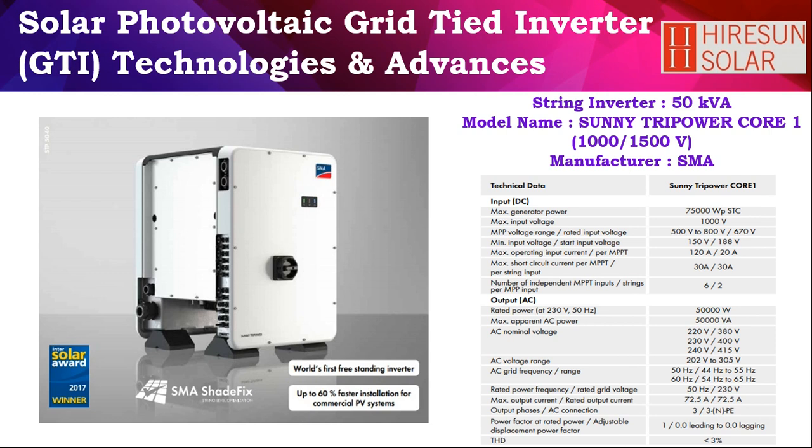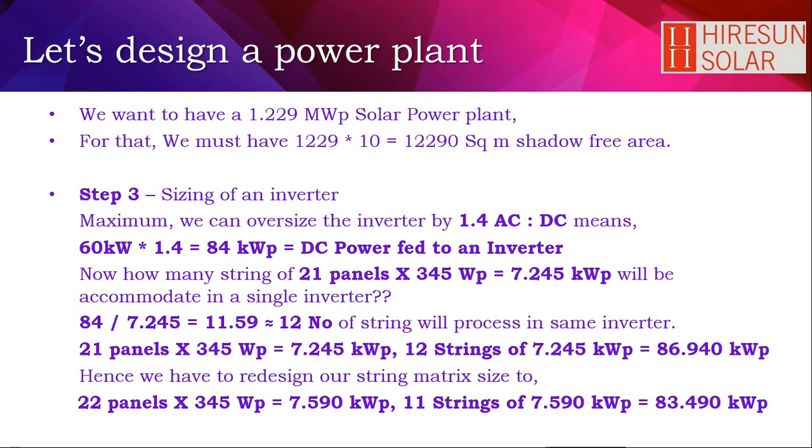We are considering the maximum output current and rated almost similar, because this is the shortest transmission from the panel to the inverter. As I mentioned that the 1500 volt is accommodated over here, so it can withstand up to 1500 volt also. Then accordingly this design will be changed.